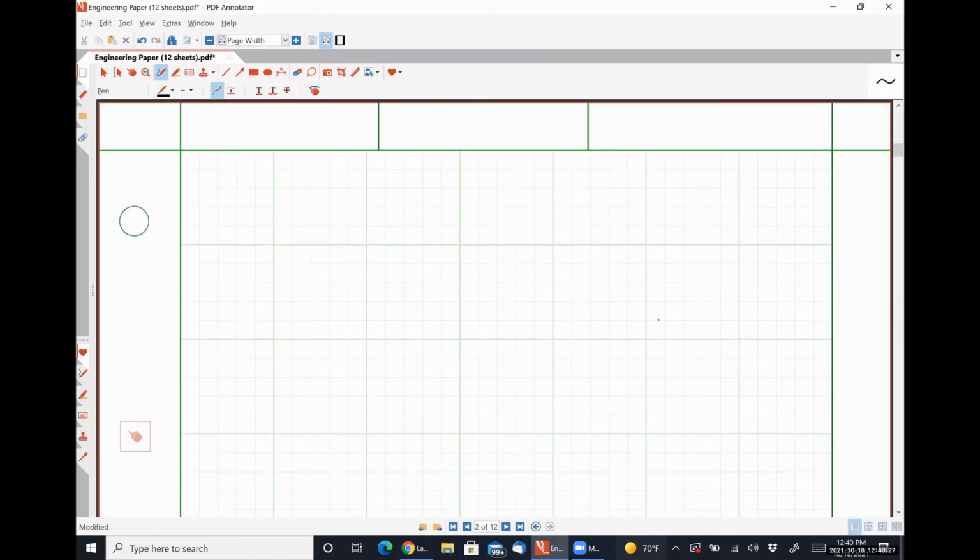So our small signal model is going to look something like this. So let's say that this guy is my gate. This is going to be RA in parallel with RB. Here's my small signal VGS between my source and ground.